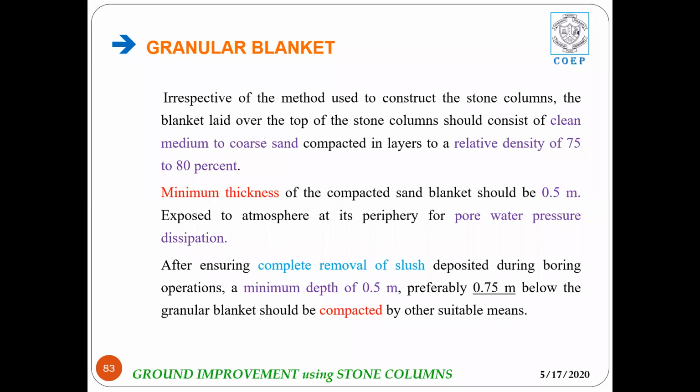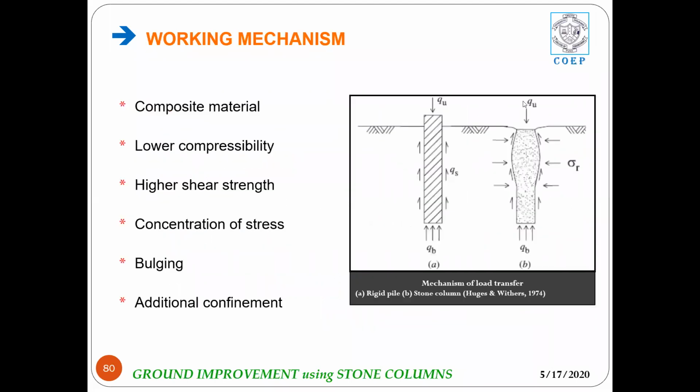When the stone columns are subjected to loading, squeezing of the soil starts taking place, and deformation starts, because of which bulging is also introduced.